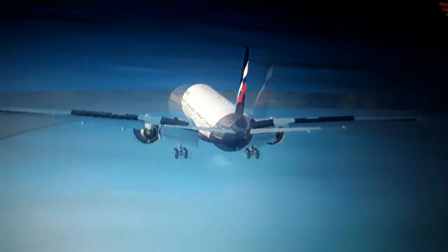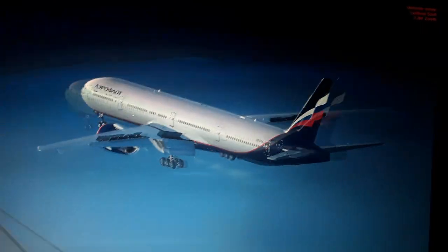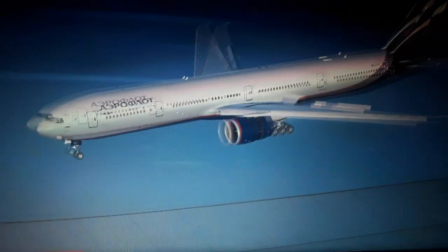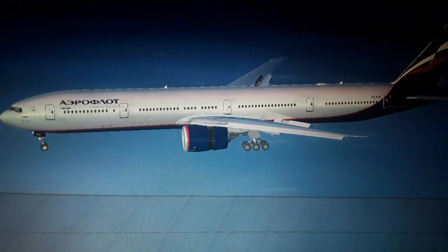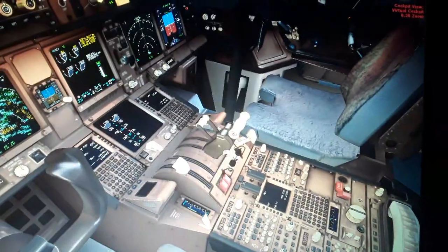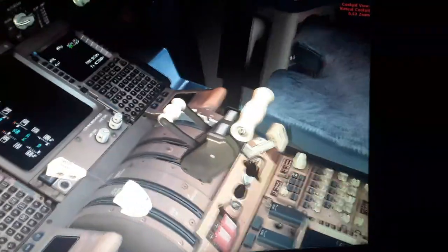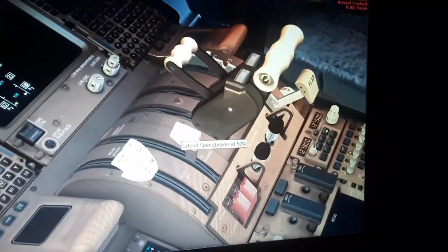Slow down this airplane after landing in the touchdown, or in a rejected takeoff. After this, you cancel the thrust reverse. Also, if you have the idle setting for the engines, you can extend the speed brake. You can see the speed brake here.